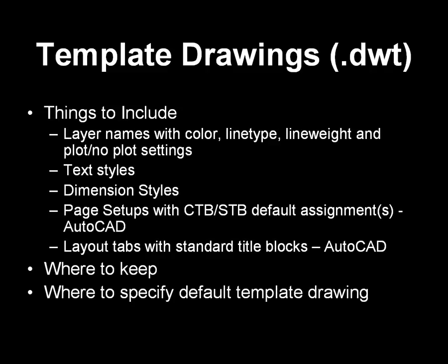So we'll move on, and let's talk about now, again, you've got all of your CAD standards set up, and you start your files with template files. But what happens if you're like me and you have a really bad habit of purging everything? Once you purge, you're going to get rid of any unused layers, any unused text styles, any unused line types. And then, of course, what's going to happen? You need that particular layer that you didn't think you were going to need. So we have a couple of answers for this.